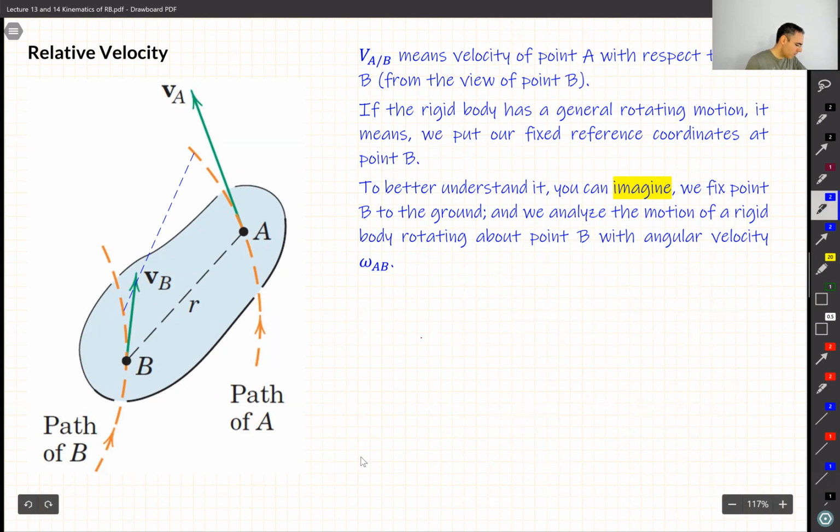So this is going to be B prime, and this will be A prime. Obviously, what we notice is the whole thing is moving, and also this line AB, its angle has changed. So it means there must be a change in the speed. So there is an omega then, because if we draw a line, it's going to change angle. So there is a rotation.